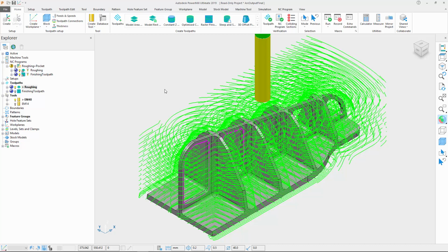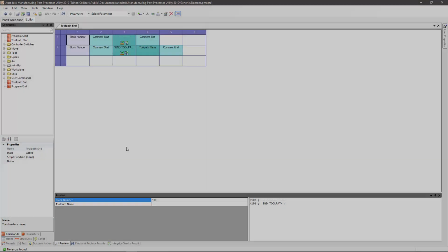This was detrimental to surface finish, as more facets would appear in filleted areas. It could also prevent programmers from making programming changes on the controller, such as adjusting tool radius wear compensation values. This latest enhancement means Powermill now supports arcs output on 3+2 toolpaths.